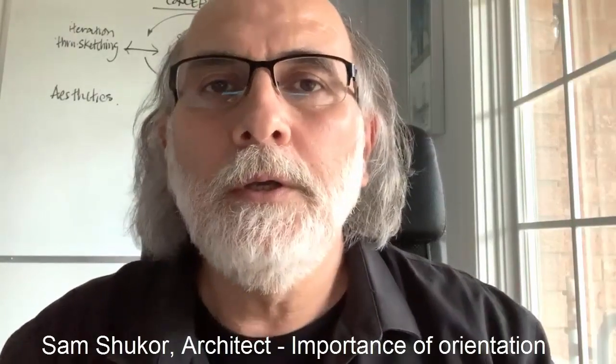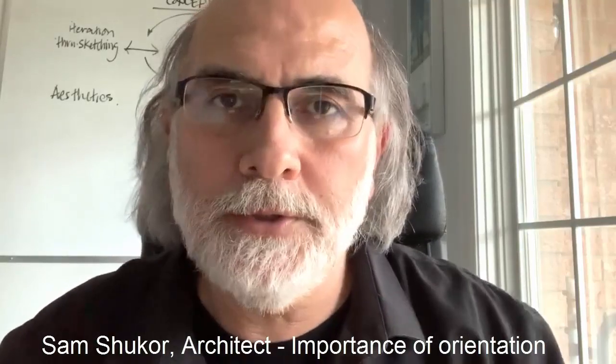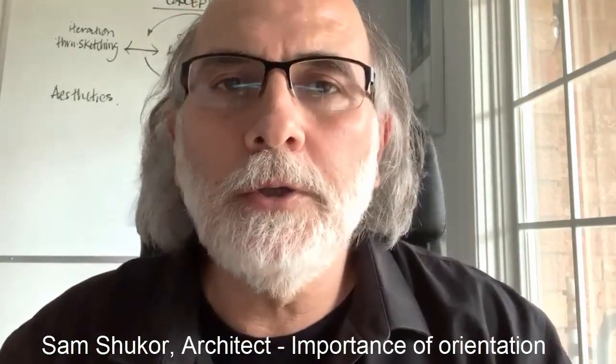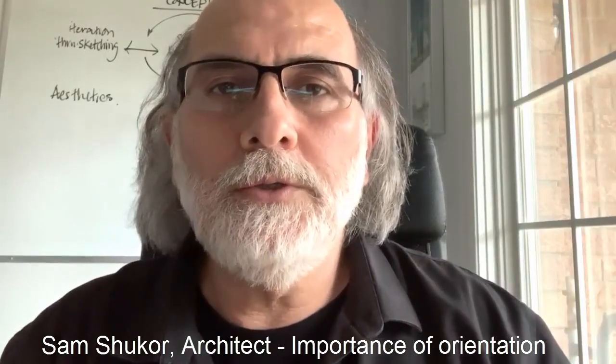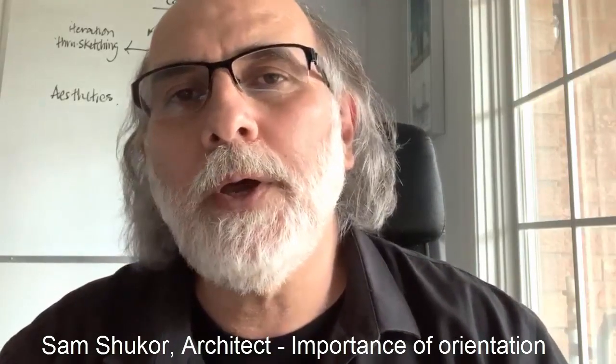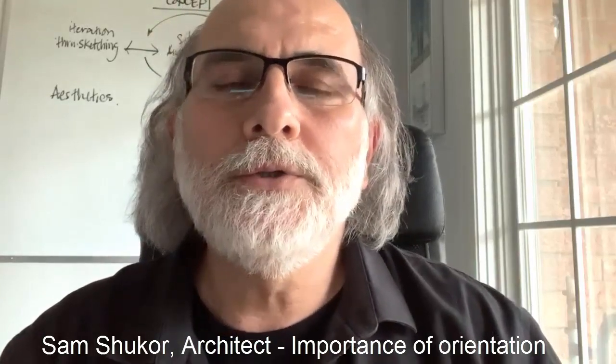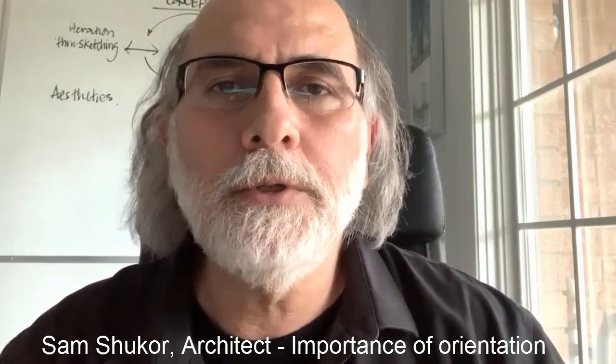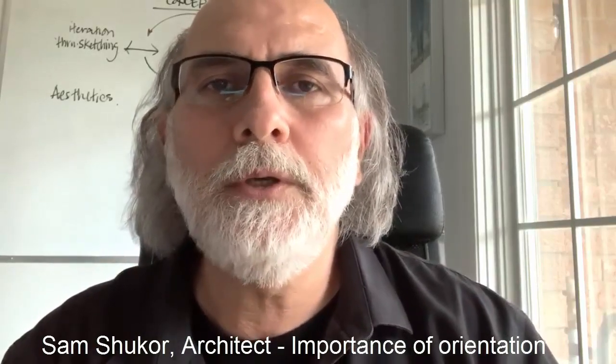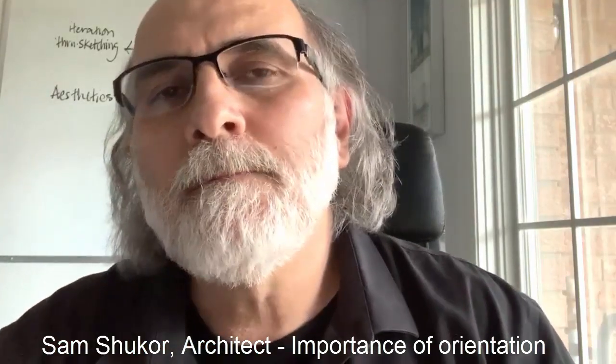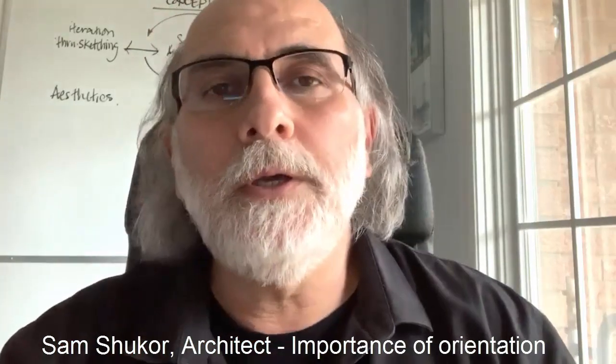Today I want to talk about site analysis. Now, site analysis is a vast topic. There are hundreds of things that you have to check on site in order to ensure that your building takes into consideration all the aspects around site. I mean, from the ecological impact all the way to the geotechnical impact, the type of soil, the slopes, the contour lines, the orientation, the views, the wind speed, any elements that cast shadow, and so on and so forth.